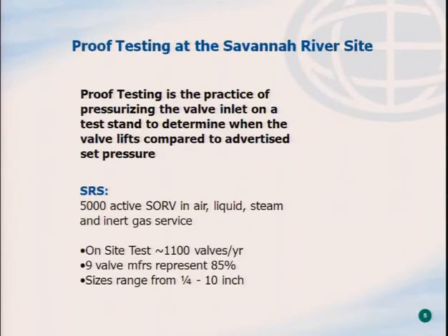Okay, the proof tests, we basically test or take the valve out of the field, deliver it to our valve shop. We don't clean it, we don't do anything with it except mount it on a testing frame, and look at what the pop pressure was. Testing on site, roughly 1,000 valve tests per year. 9 manufacturers represent about 85% of the valve population. And it's a very diverse population of valves that we have.